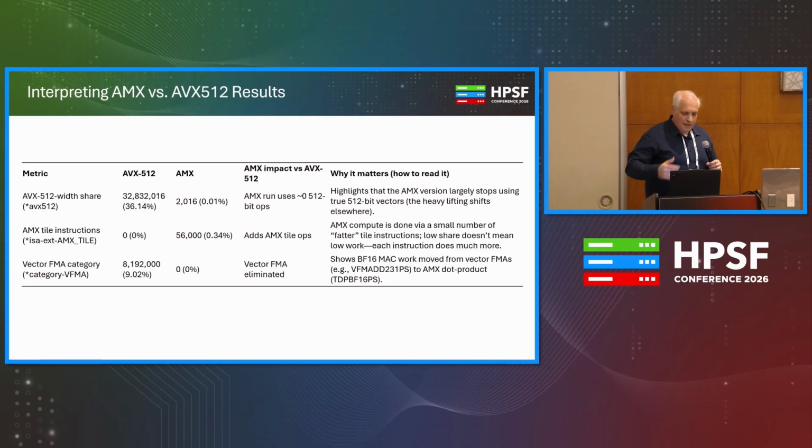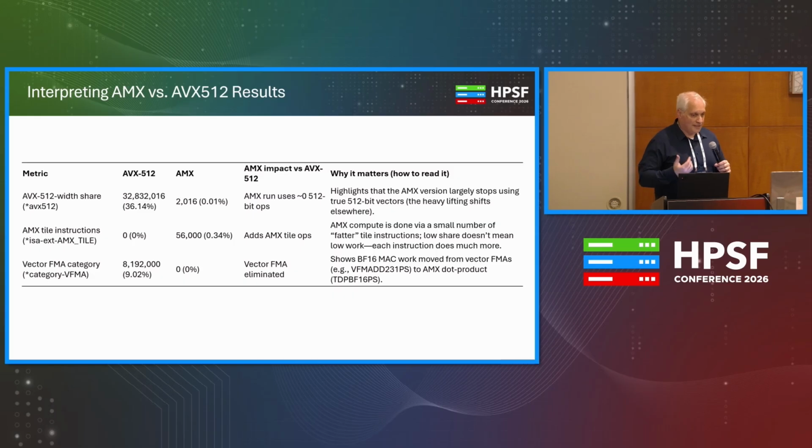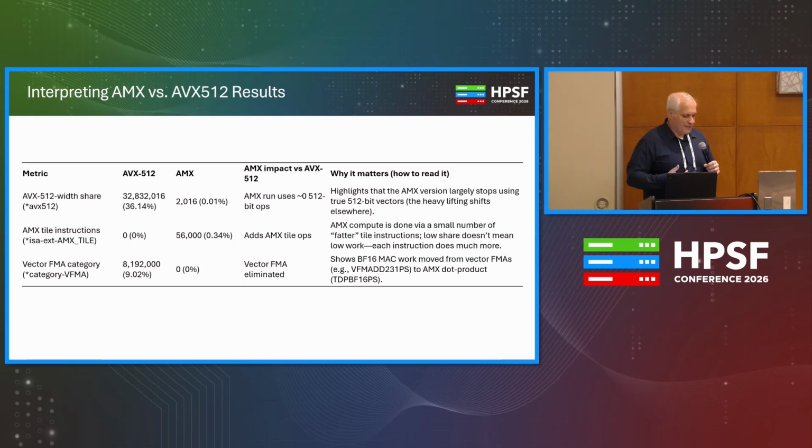So again, a quick summary, pretty much just reiterating what we talked about. Much fewer instructions, so you have a lot more cycles to do other things you want on the CPU. Benefits on memory overall. There's a little impact on stores, but net, significantly fewer memory operations, so less pressure there. Ultimately, these together say you're going to see a nice boost on AMX when you're doing a lot of matrix multiply versus standard vector types of operations.